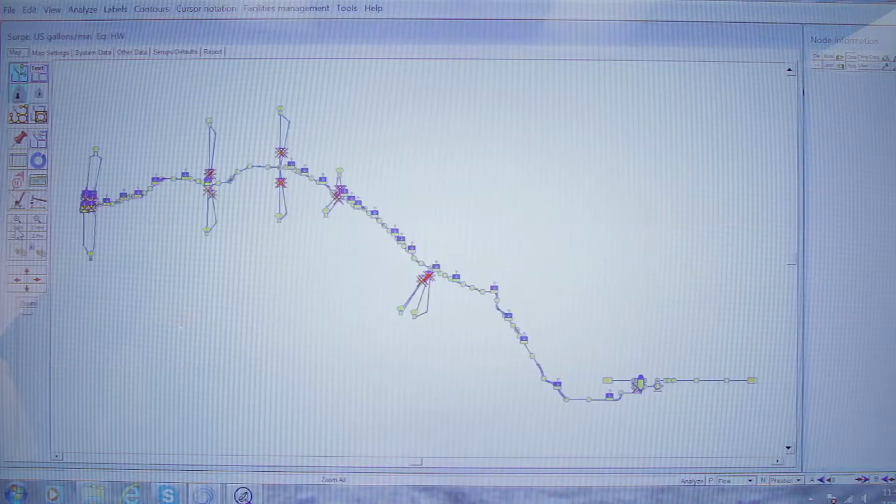Every time that negative wave would go out, our air vacuum valves would open up, which is introducing air into the system and air out of the system. Because it's a frac water application, we want a zero discharge through the air vacuum valve. So if we can keep the line positive and not rely on the air vacuum valves, we can minimize them leaking in the field.